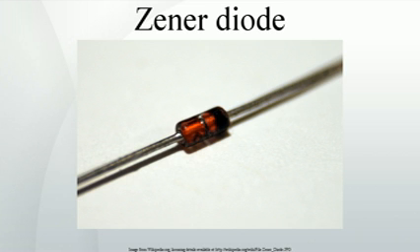As a result of the reduced barrier between these bands and high electric fields that are induced due to the relatively high levels of dopings on both sides, the breakdown voltage can be controlled quite accurately in the doping process. While tolerances within 0.07% are available, the most widely used tolerances are 5% and 10%. Breakdown voltage for commonly available Zener diodes can vary widely from 1.2 volts to 200 volts.